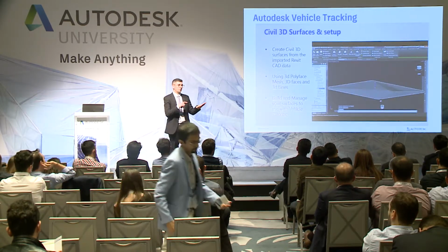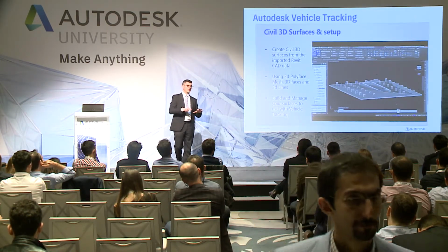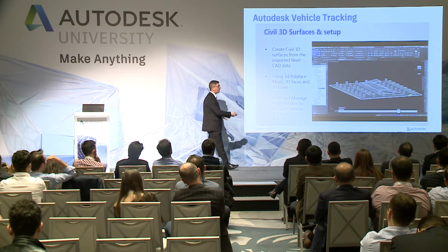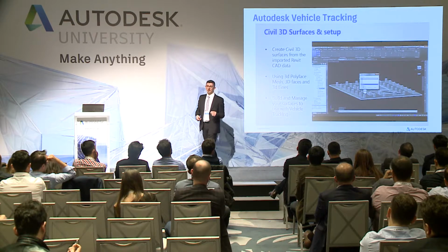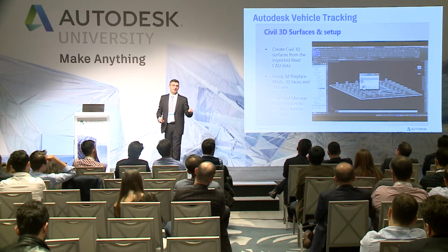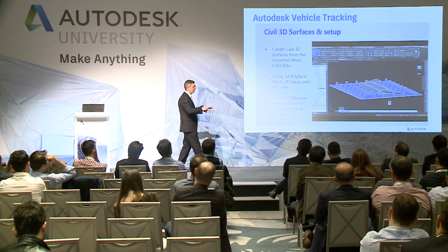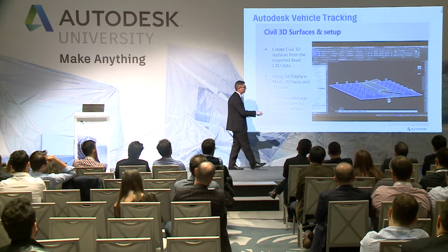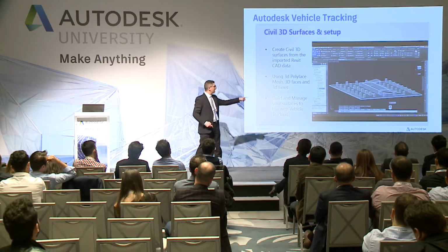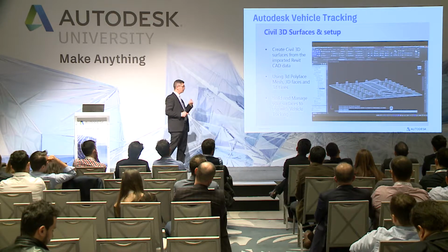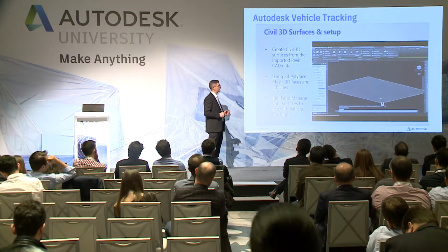Sometimes it's difficult because you need to manage this type of representation, where you have the ramp to go from one floor to another floor. If you click only the surface from the ramp, it is wrong because you don't have the right triangulation. Sometimes you need to select with more detail the elements that you need to create the surface. I can start from the floor, but after I need to add a polyline that is the boundary of the ramp, and then I can select like this one. And the result, you can see, takes less than 1 minute.